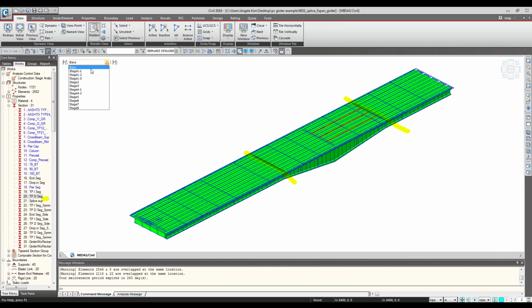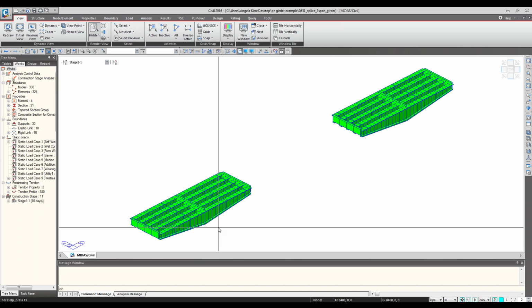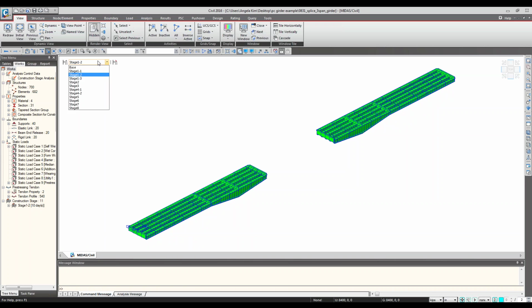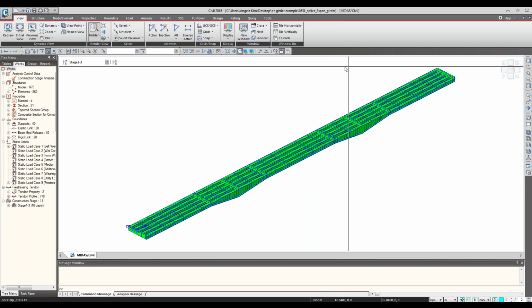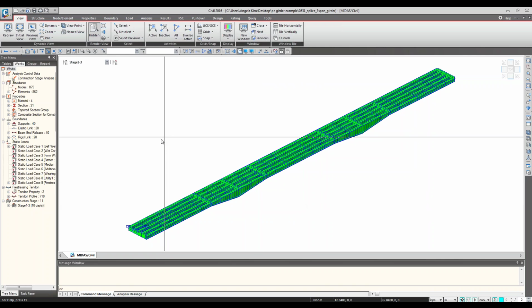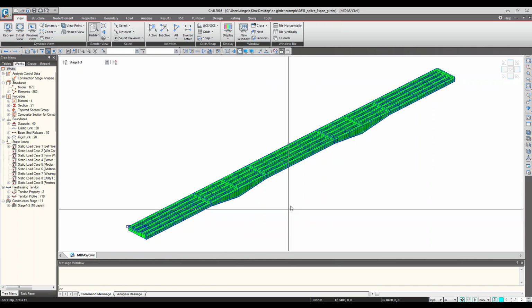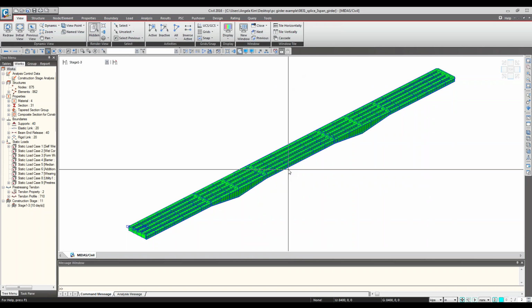So we have a different splice girder point, like 1 and 2 here. Makes sense, right? So when you actually look at the stage effect like this, the substructure portion came in first, and then you can also erect the end parts, and then you can also erect the very last portion. And this erection sequence, right now, is simulated to be symmetrical. If you need to, you can sequence them so that one span comes in first, and after how many days, the next span is erected and so on.